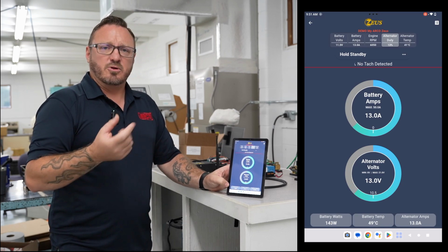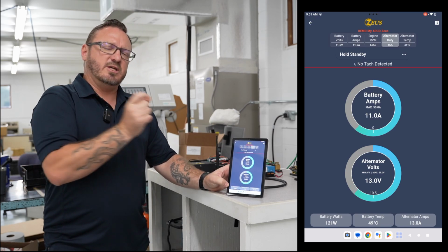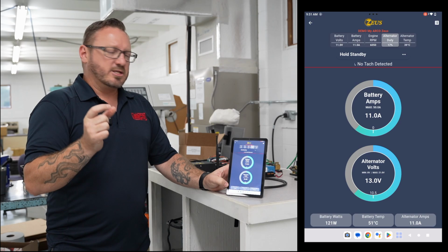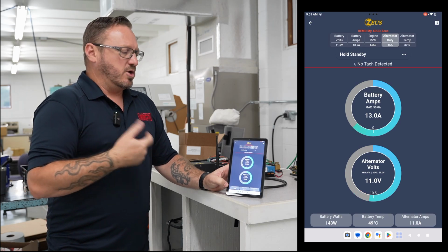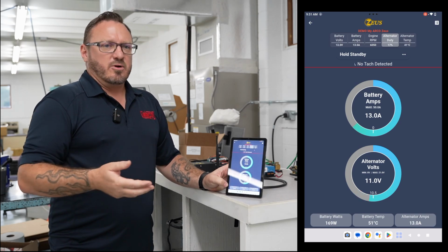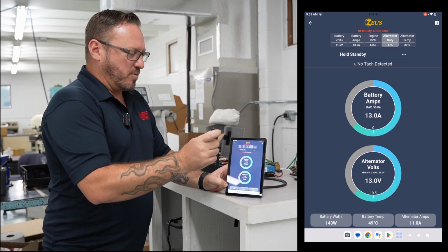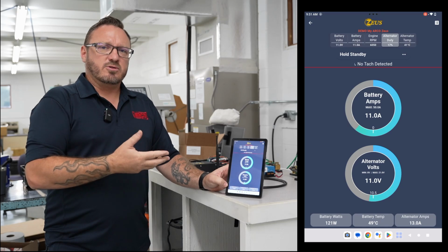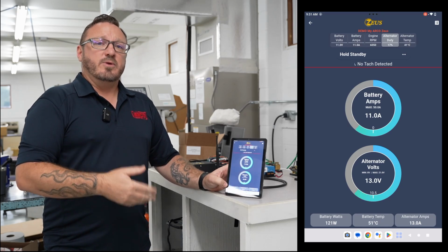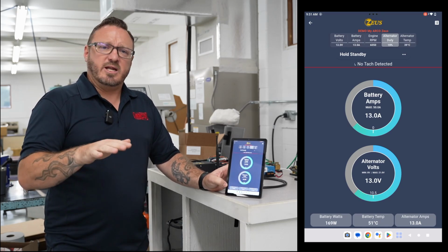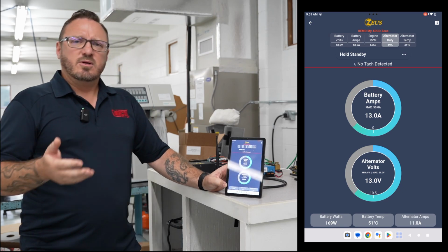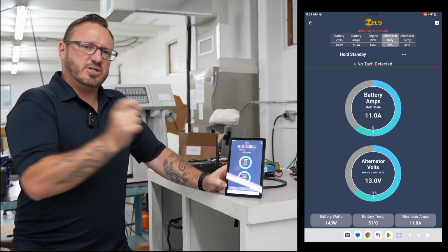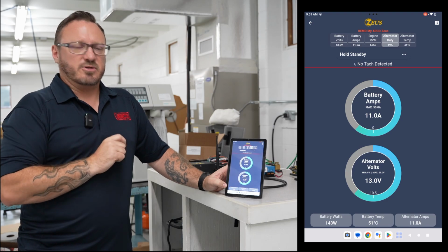Now you'll also notice a little gray box. That little gray box is going to be shifting when you're charging, and it's going to be telling you your limiting factor. So let's say you're at 800 RPM, you're at idle, and your gray box is over your engine RPM. That's telling you to get more power out of your alternator to charge your batteries, we need to increase your engine RPM. But if you want to stay at 800 RPM or 850 or if you're idle, that's totally fine, but that gray box is going to shift and tell you what your limiting factor is.